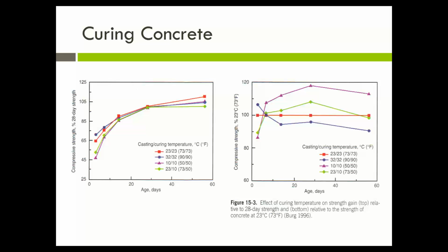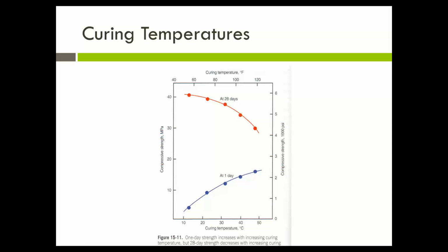Similarly, if you look at what that does in terms of strength, you get that increase from curing. But if you don't maintain the moisture, then you won't have this effect. And if you let the concrete drop below about 10 degrees, it doesn't do very much.